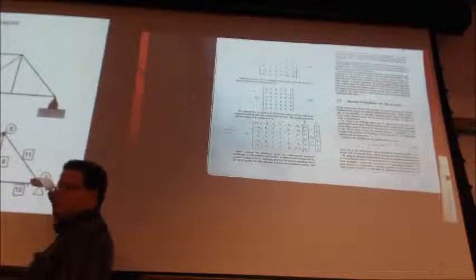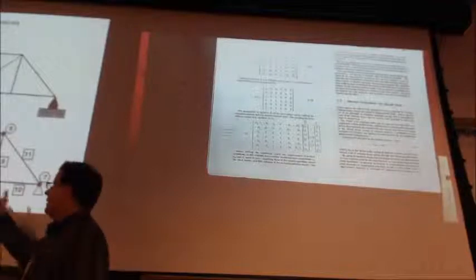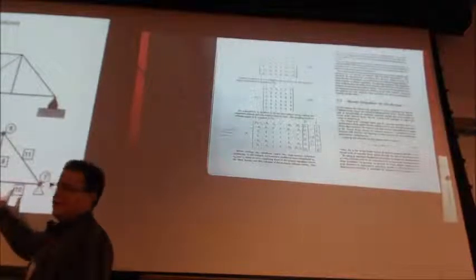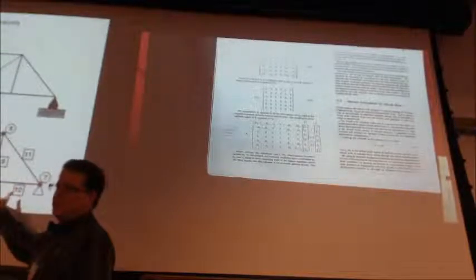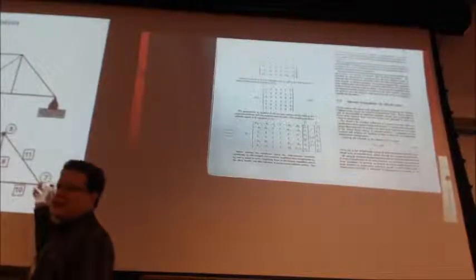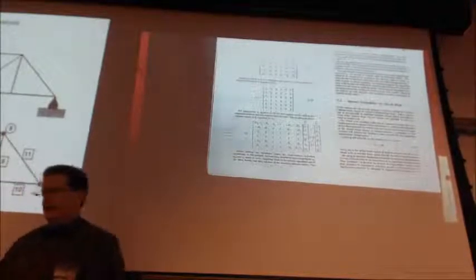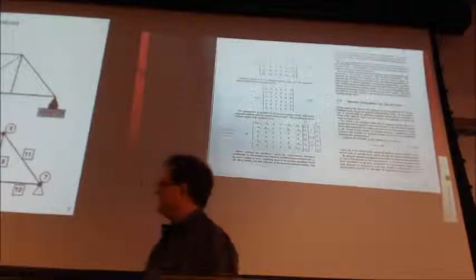Whereas if we leave this as a roller so that it can move in this direction, and only clamp one end completely, then we can solve these with analog calculations much more quickly and easily. Now the computer doesn't care, and yes, you could constrain it completely at this end, and it'd be fine.